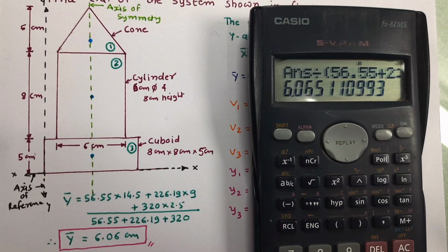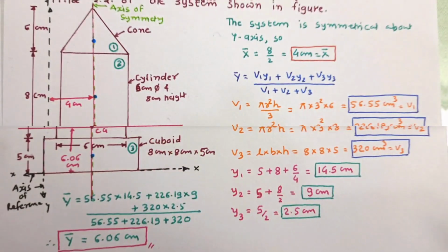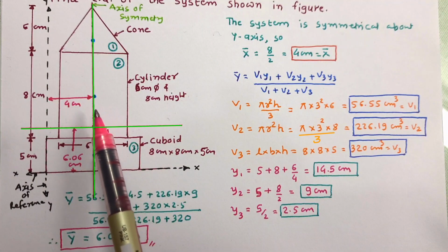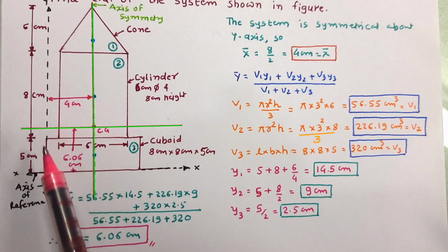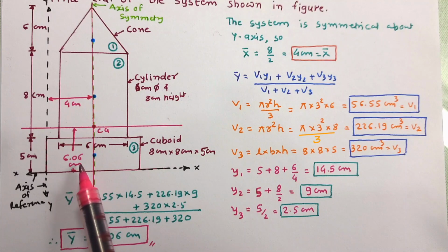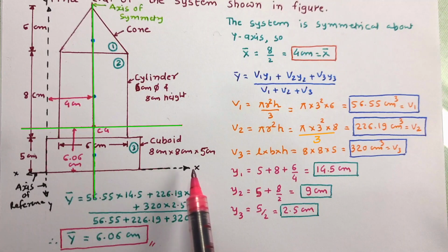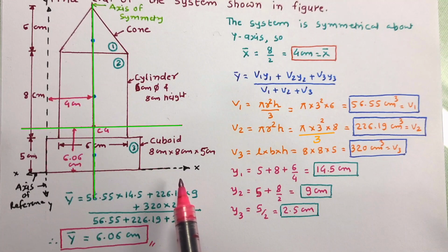Now let us mark the centroid in the figure. So this is the centroid of the figure, which is 4 centimeter from reference y-axis and 6.06 centimeter from reference x-axis. This way you can solve such problems.